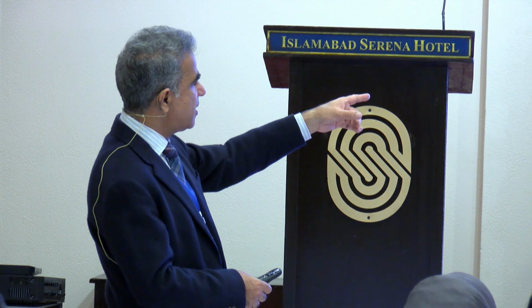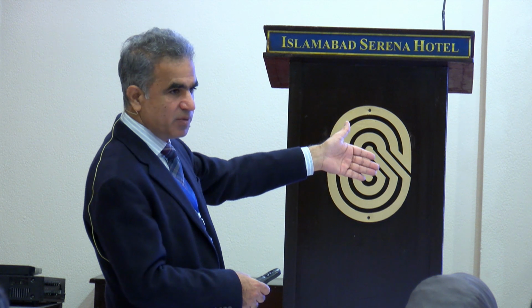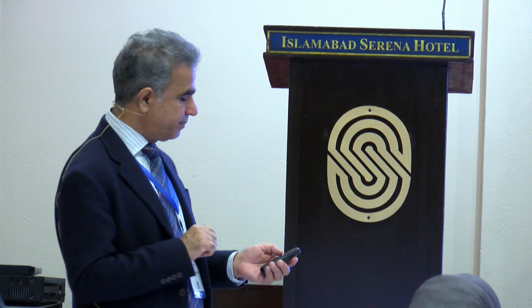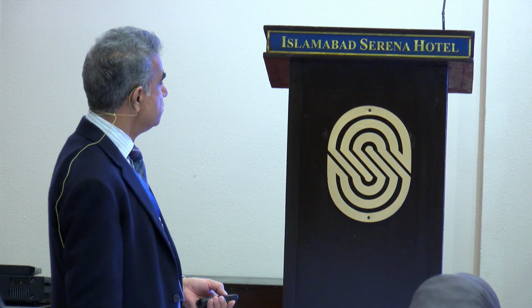So this is the tool body, like a pipe or metal rod. It has a device which generates sound waves. We call it a transducer or transmitter. In ultrasonic we call it a transducer. In sonic, at a different frequency, we call it a transmitter. It basically sends beeps or sounds to the formation. At different frequencies there will be different responses.